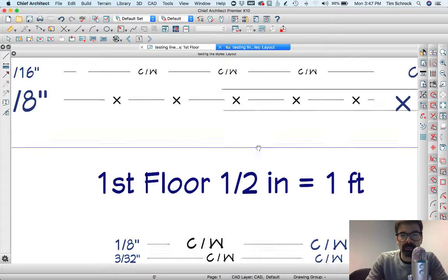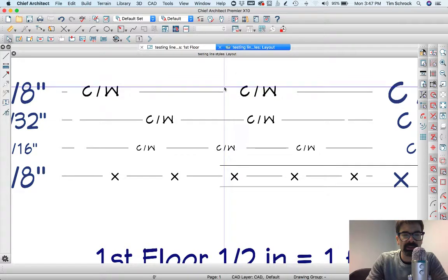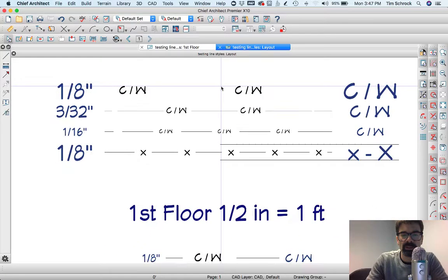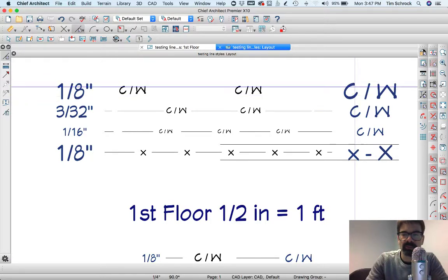Now, coming up here, looking at 1/2 inch scale, notice when I sent it at 1/2 inch scale, the CW large is not as tall as what I would have expected 1/8 inch type to be. Now, I did leave this at 6 inches, so when I send it at 1/2 inch scale, this is actually going to print 1/4 inch tall. This text will actually print out full size, measured on a tape measure, 1/4 inch. So this would be measured at 1/8 of an inch.